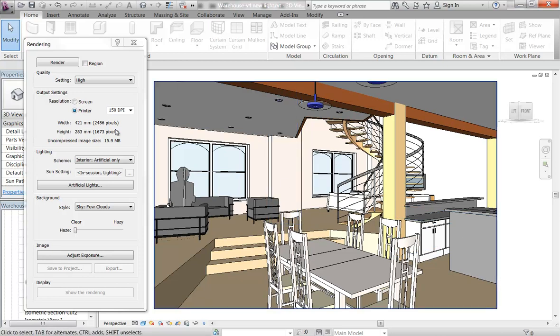So it's a lot of pixels, essentially. And so you can get away with lower resolution sometimes. A3, believe it or not, is fairly large for a full rendered image. So you could quite easily go down to 150 DPI. If you wanted an optimum presentation, then maybe you could go to 300 if you had a lot of time to render, because this would take a day to render.